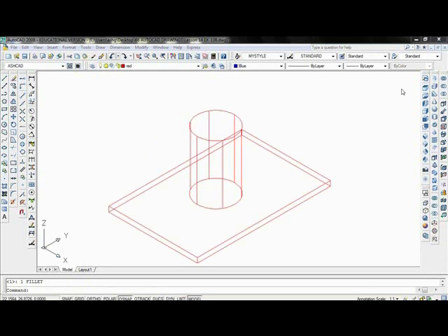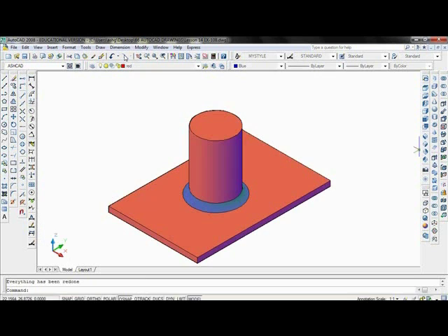Now I'll show you how to fillet solids in 3D space. This drawing shows a cylinder and a small box. The objects are union together. I'll type fillet and pick the bottom edge of the cylinder, then type 0.25 for the fillet radius and press enter. And now I think I'll create the drawing for exercise number 22.